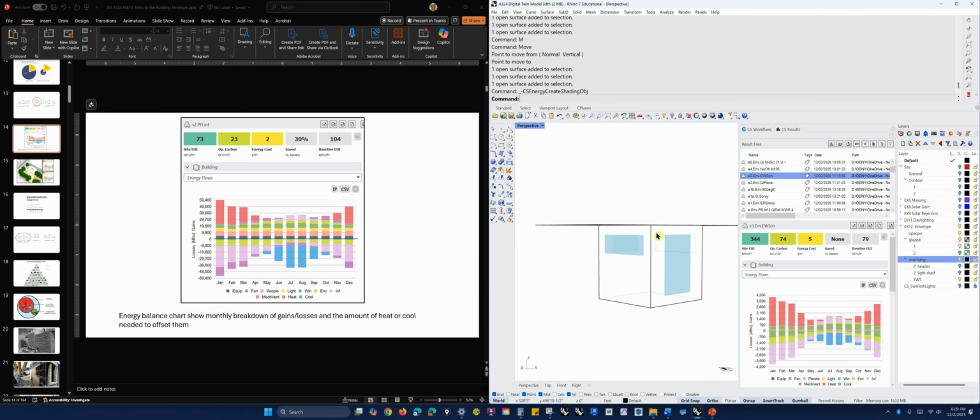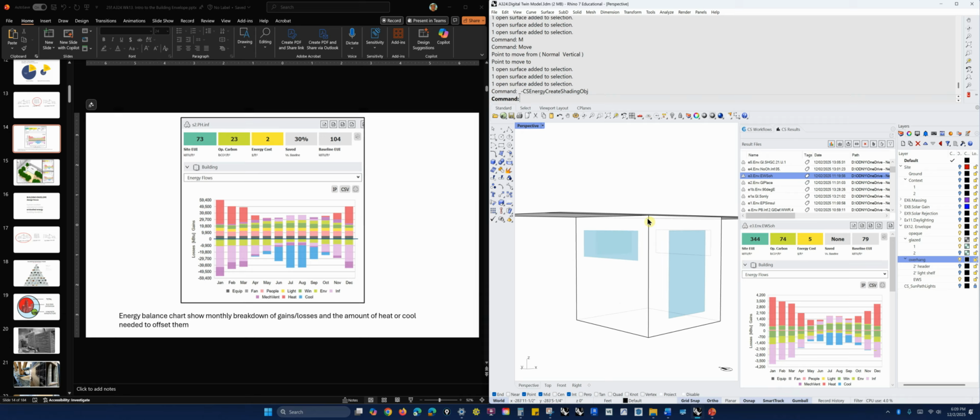And if we spend a bunch of effort to surround this insulation, but then we don't, which most of the time I've seen with you guys is the case. You've got your particle board just loosely taped on here, and you've got a big gap at the corners. A lot of air is going to circumvent that foam, so if it's cold outside, that air is going to go in and pretty quickly fill that little space.